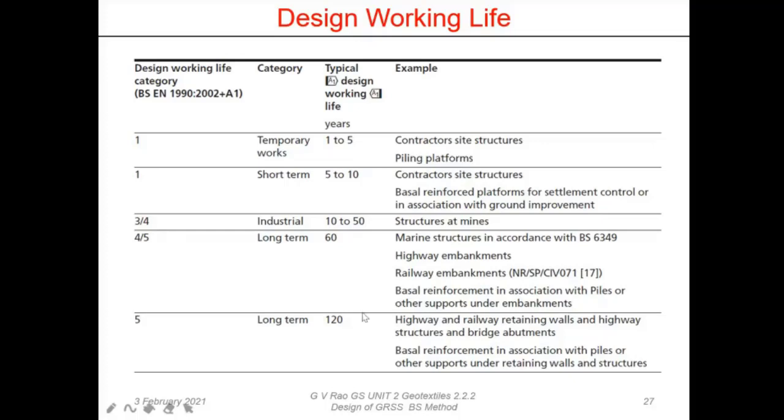In other cases, like vessel reinforcement, we find that the structure is a permanent structure, and the life of the structure is like 100 years. But we know that the consolidation will occur in 5 years, in 10 years. So that means the loads going to the reinforcement have to be borne by the geosynthetics only for 10 years. After that, the soil is consolidating and gets its own strength, so actually the geosynthetics is redundant. In which case, what we are going to do is apply a lower factor of safety. That means we are able to give more allowable strength actually. So that is why design life is important, which is not the case for normal concrete structures.